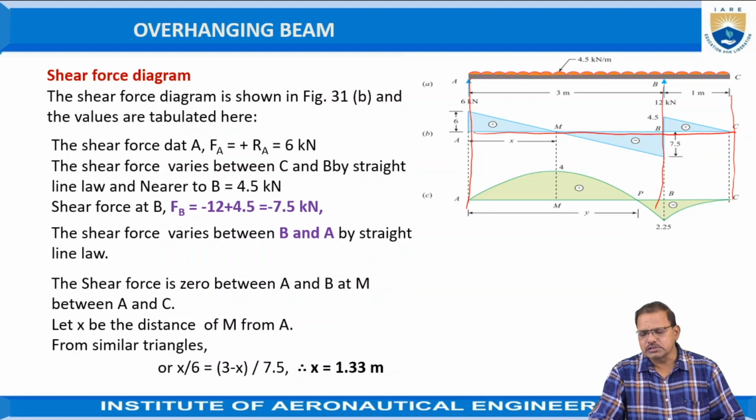Since the shear force is positive for the cantilever beam, and for the simply supported beam, toward the right side is negative and toward the left side is positive, keep sufficient space above as well as below the reference line. After drawing, the shear force at the free end of the cantilever beam is always equal to 0 because of the uniformly distributed load.